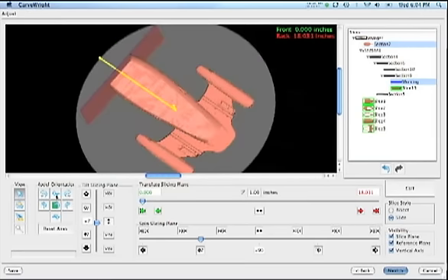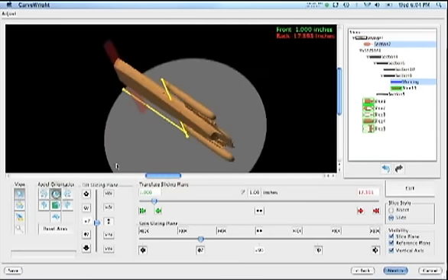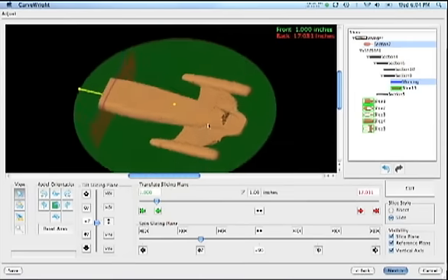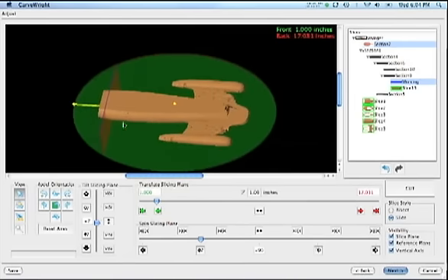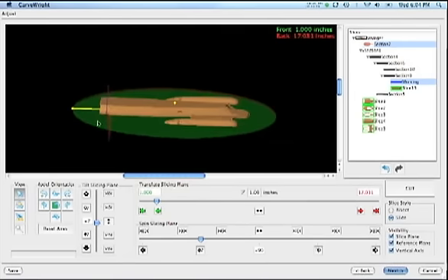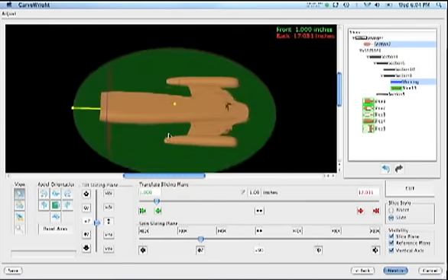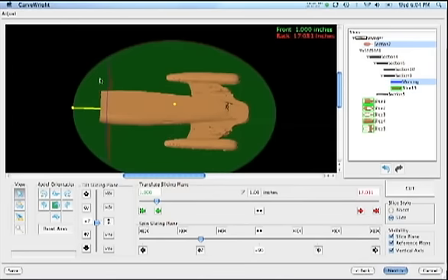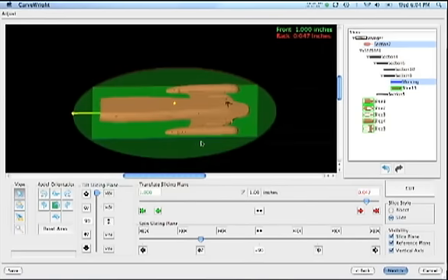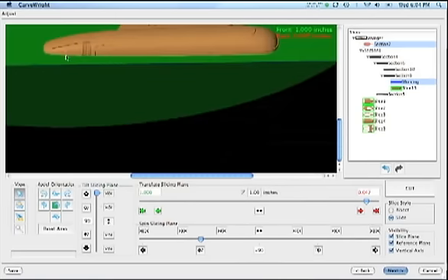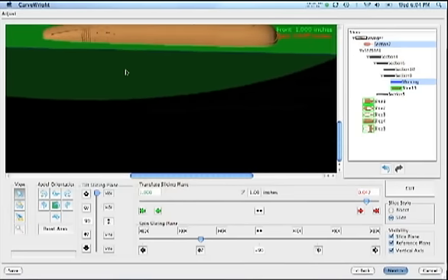which we need to flip around so it's facing the right way. And that little bit of 7-degree taper is going to work well for us on this side too. With that straight up and down edge, with that little bit of taper there, we'll be able to glue that back up to that other section without too much trouble. So we'll rotate our plane up to the top, and we'll go look at this slice. It looks like it's going to give me a little bit, just under an inch.